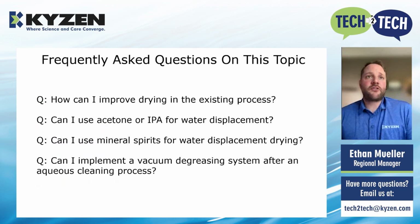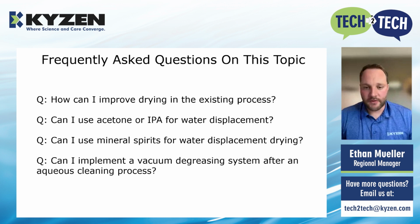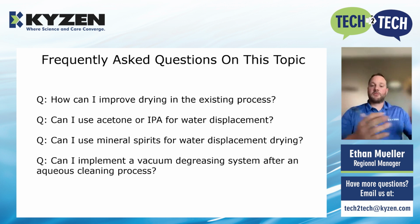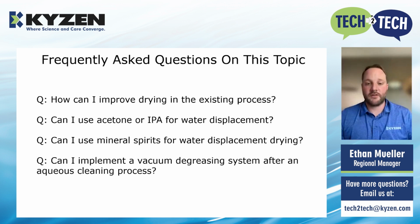QC. Some frequently asked questions on the topic: how can I improve my existing drying process? You can look to make some investments in increasing the overall flow, the number of air knives in an aqueous process, or you can implement that downstream solvent process where you're using it for water displacement. There are a lot of different ways that you can improve the process. It's just dependent on what you have and what you're going for.